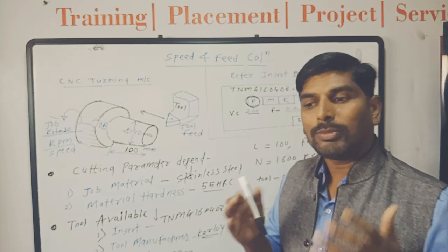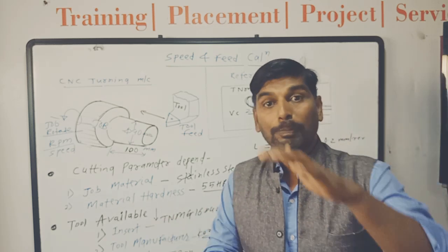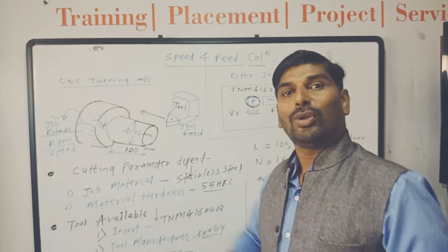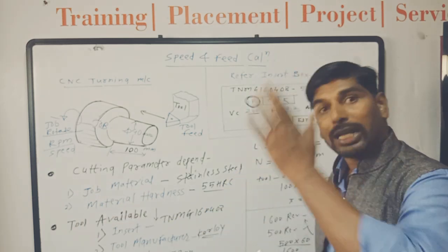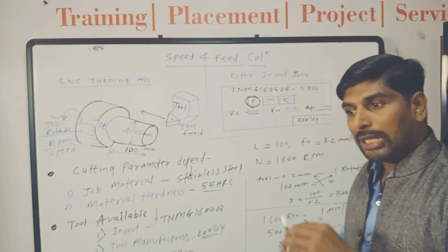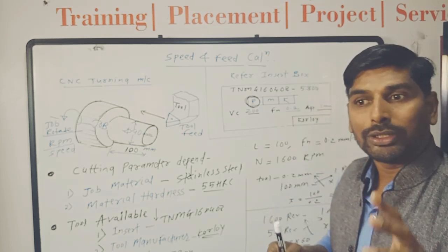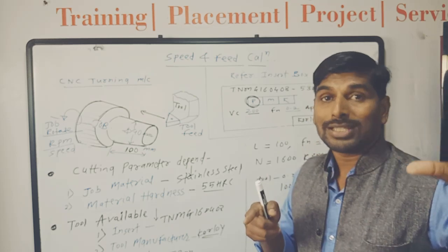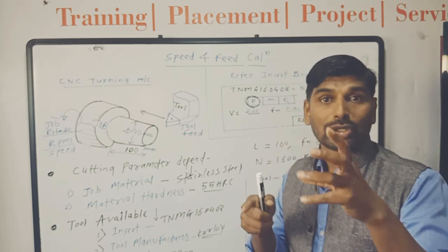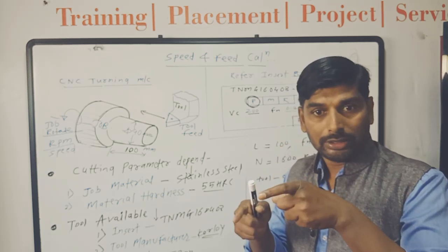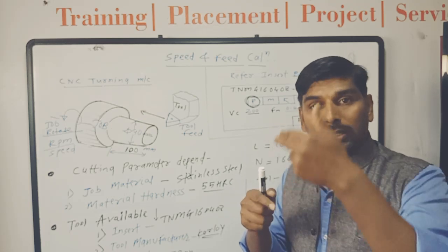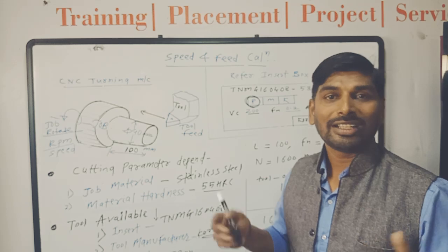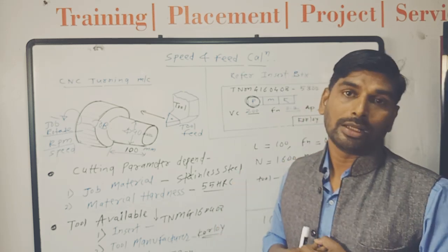But with some jobs, if your job has a 500 mm diameter and 1000 mm length, sometimes loading and unloading time is more than cutting time. But that you have to count in your cycle time. Sometimes your job has some special operation, and due to customer demand, you have to check each and every size. There are some critical dimensions like bore size. You have to go with an air plug device, or check with a thread plug, and so many other instruments used to check the job. That checking and inspection time also has to be added.